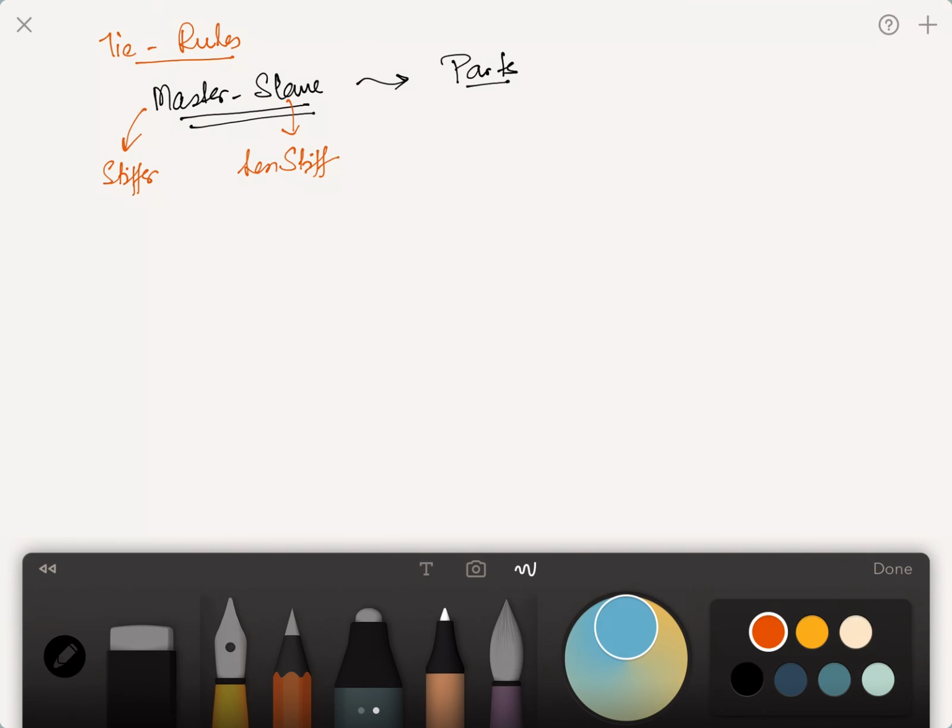This is a rule. The second rule is that the meshes or element sizes, I'm going to write it as element edge length because it's obviously at an interface, should not be too far from each other.